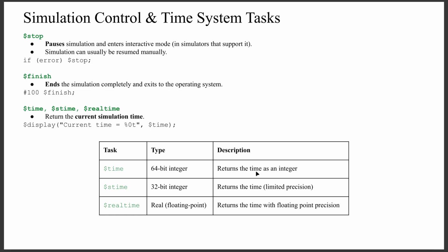Simulation control and time tasks. So $stop, self-explanatory, just pauses the simulation. $finish ends the simulation, and $time just displays the current simulation time. And these are the different time types: 64-bit, 32-bit, and a real or floating time.